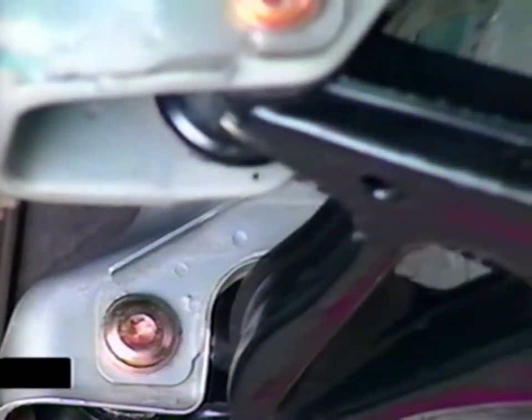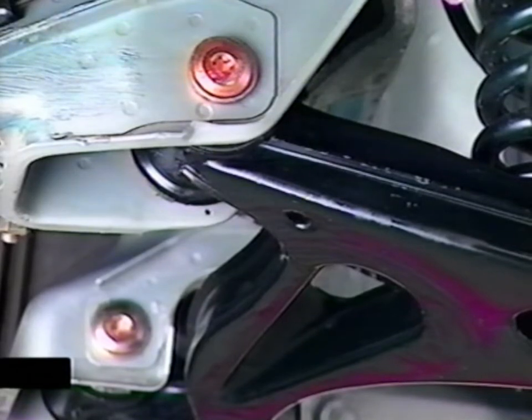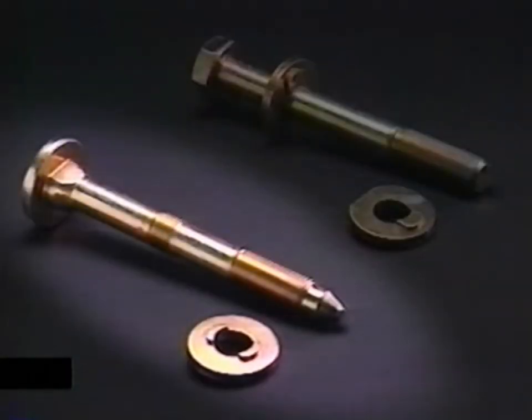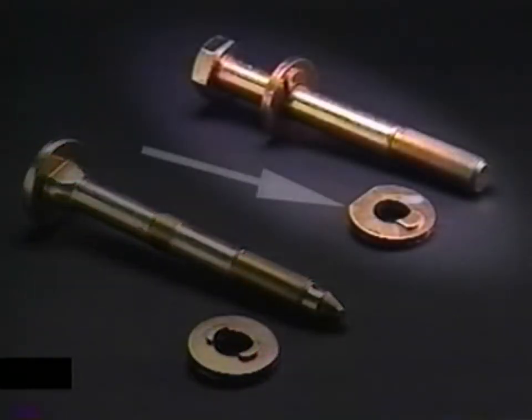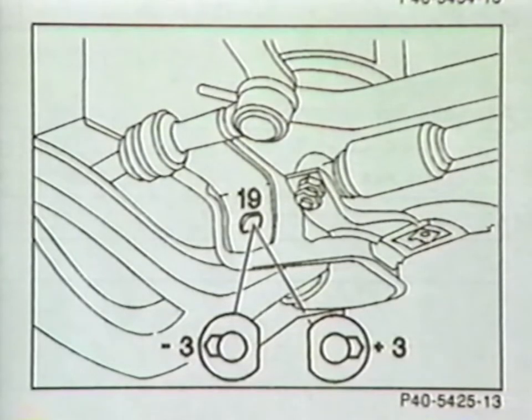Although the need for camber and caster adjustments during factory production has been eliminated, if a subsequent measurement should indicate that either adjustment is out of the specified tolerances, a correction is possible using a repair version screw and washers. Up to July '93 production, the control arm mounting hole is oblong, and a repair version mounting screw is available that is designed using offset tab washers.